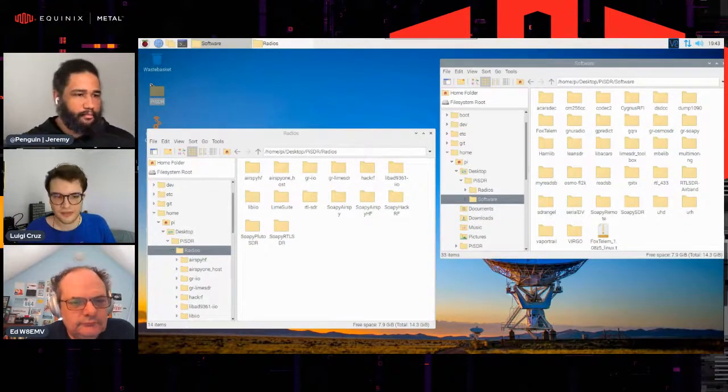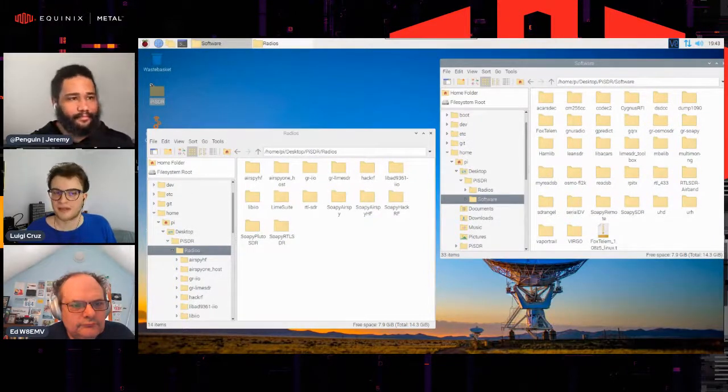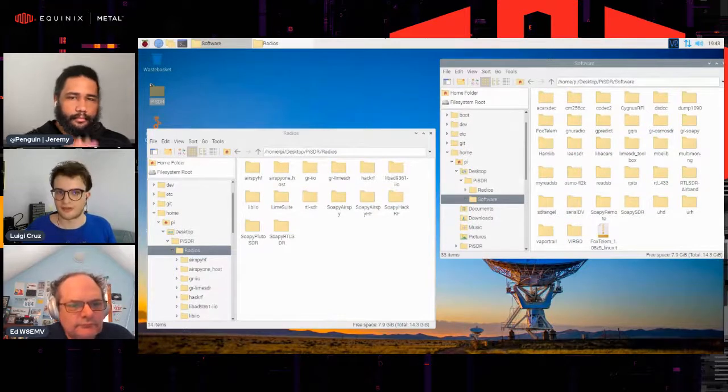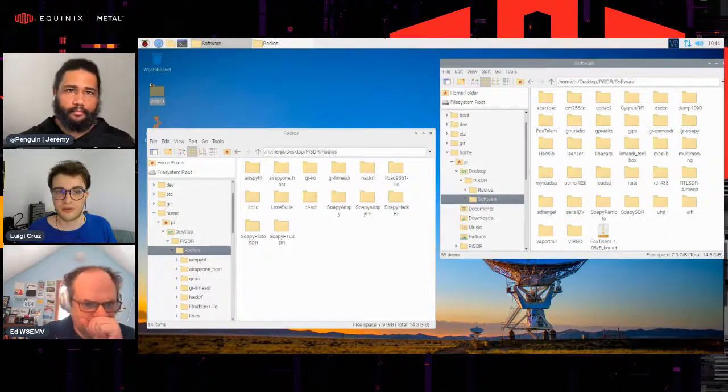Yeah, the rockets tend to use the S-band signal, which is from 2.4 gigahertz, and most of the high-speed modern satellites of the lower orbit use X-band, which is 10 gigahertz. Or the legacy ones you can receive at home using the RTL-SDR at 137 megahertz. So it's quite low, but the resolution is low, and the quality of the image is noisy.